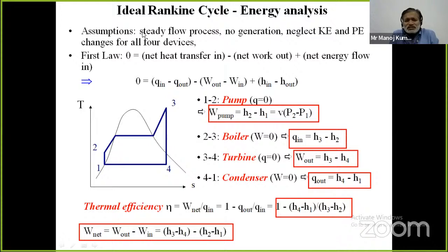So let us first consider the analysis of the Rankine cycle. Since the Rankine cycle is an ideal cycle consisting of 4 processes, 2 reversible isobaric and 2 reversible adiabatic, we just apply the steady flow energy equation across the various components, and we'll find the work output, heat input and heat rejection, etc. So in the ideal Rankine cycle, let us consider the pump. The pumping is process 1-2. This process involves the pumping of saturated liquid into the boiler.